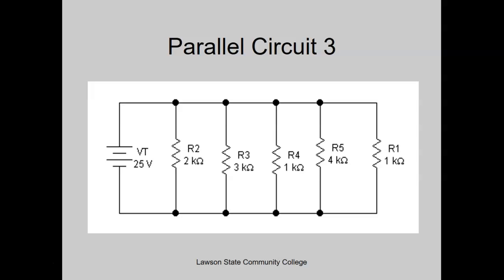I'll tell you now, guys. 100 milliamps, this guy right here, the very first one, that applies to all 3 of these resistors. That's going to divide into each of those 3 resistors. The 20 milliamps strictly applies to R4. Of course, your voltage goes to everybody, so it's 50 volts.